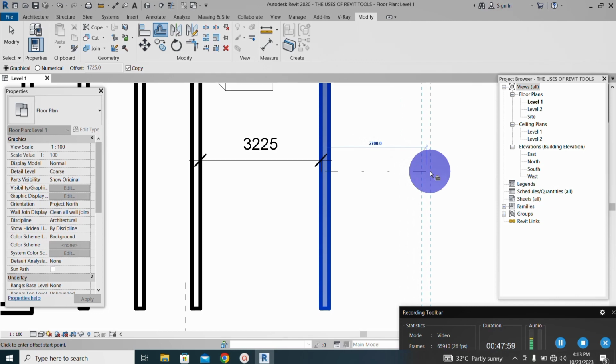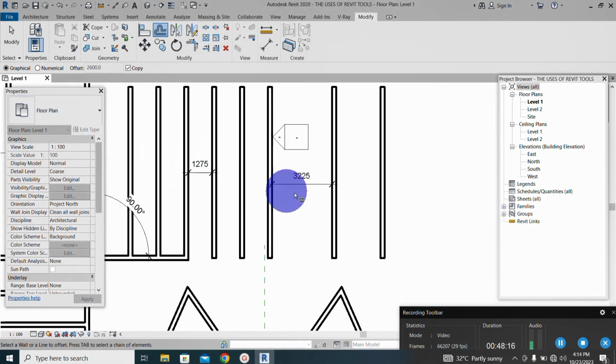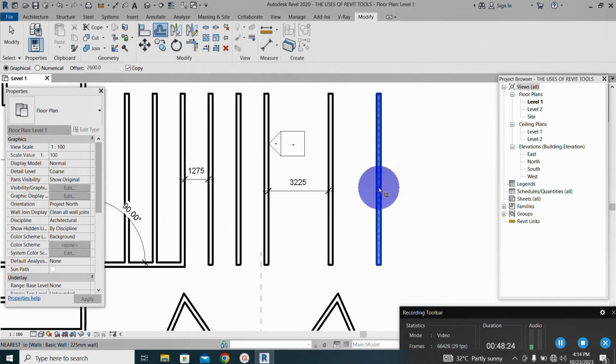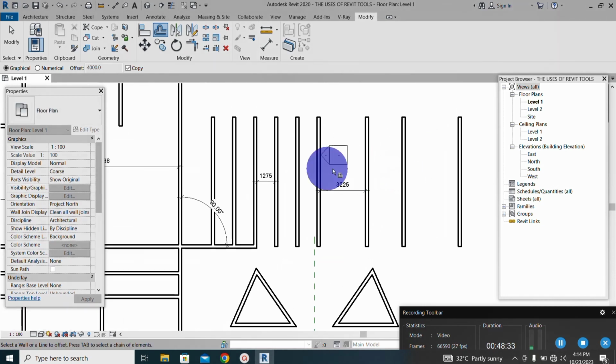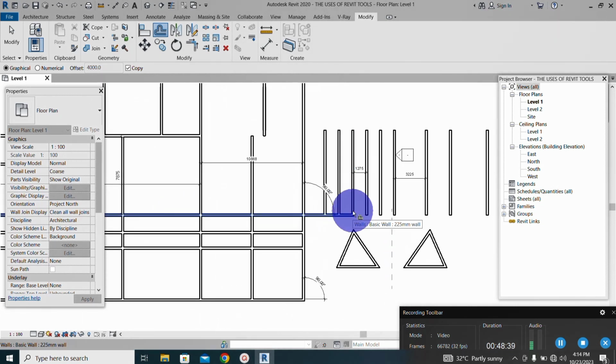Now how the graphical works is that it's going to bring out a dimension for you. Now I can decide to insert a distance by myself. Let me say that I want to offset it by 2600. I will hit enter. Let's do that again. I will click offset. You can see by 4000. Enter. That is that about offset.